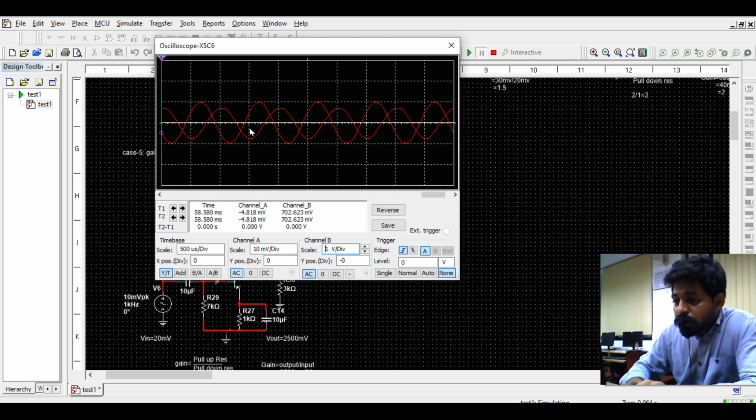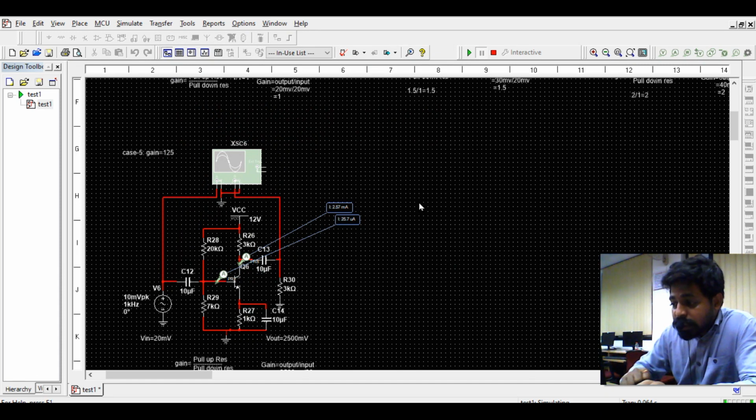shift. So my requirement is not only increasing the gain; parallelly we have to consider whether the other parameters are also satisfied or not. As a CE amplifier should give 180 degrees phase shift, if the circuit fails in giving 180 degrees phase shift, the gain is not enough for us. So here we have to remember that by keeping the bypass capacitor maybe you increase the gain, but whatever value you want, we cannot just keep it. We have to calculate the value of the capacitance over here.